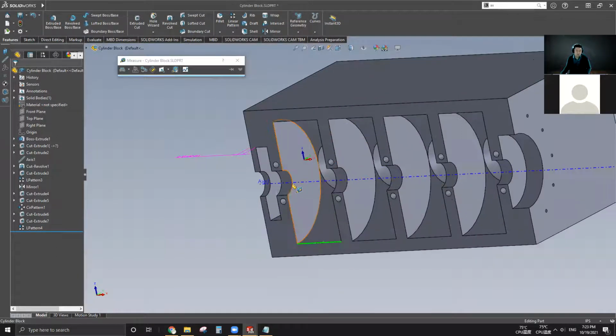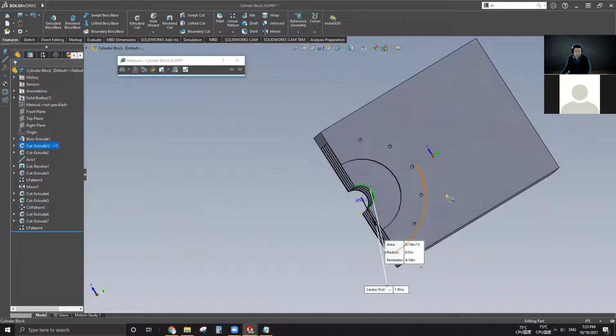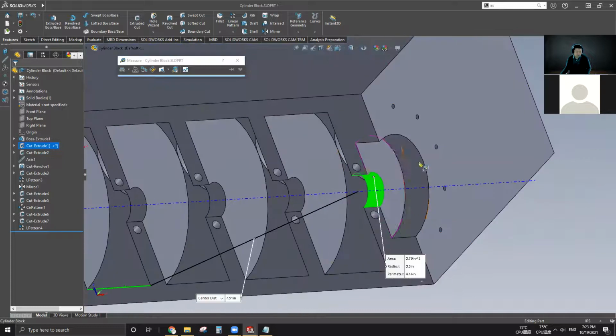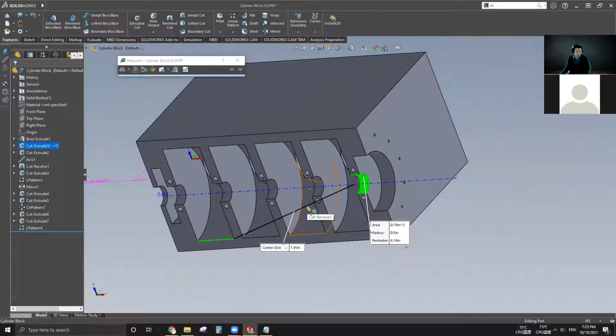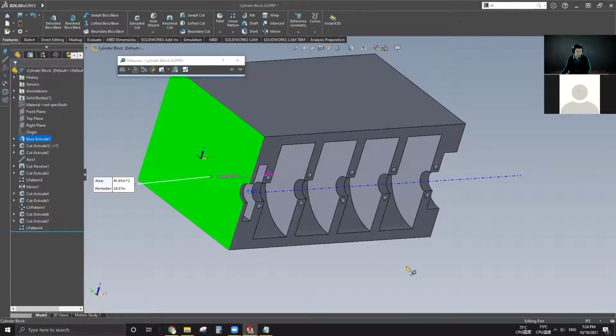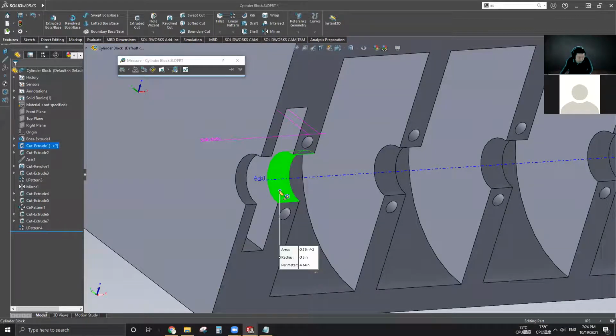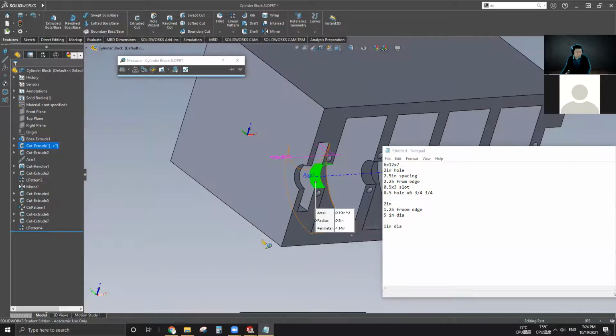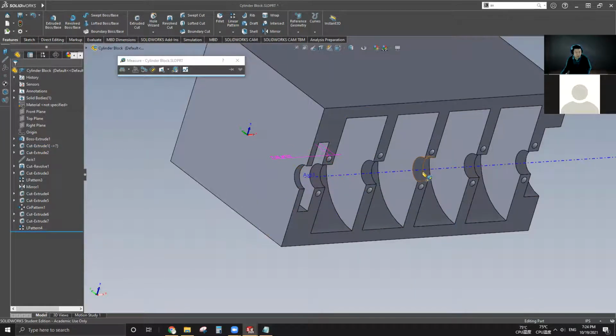Anyway, so at the bottom, we can see there is a uniform circular cut just for the shaft. It's kind of the same thing as those semicircle shaped cuts, but this one goes all the way through. So we don't need to create a plane for that. We can just work off this surface. So the diameter is 1, because the radius is half. Diameter is 1 and it's going all the way through, at the center.